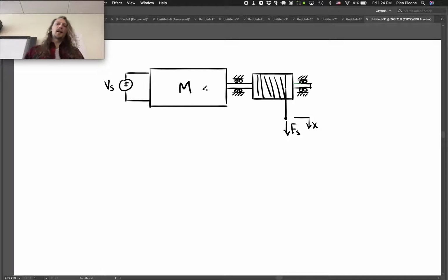So we've got this physical system, and we would like to come up with a state space model for it. Okay? From a state space model, we can find a transfer function. The transfer function is actually what we would want to put into that control system feedback loop, most likely. We would do some controller design based on the transfer function. But as we know, once we have a state space model, we have all the transfer functions from all the inputs to all the outputs, so we'll be in good shape.